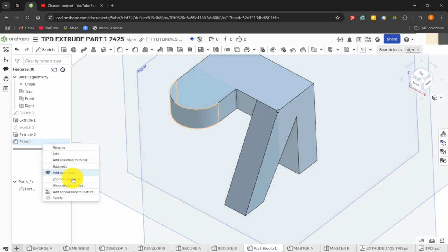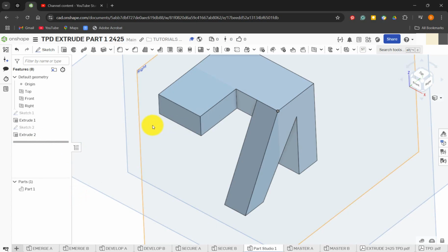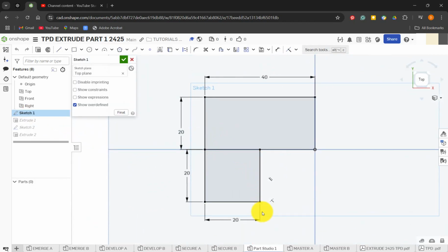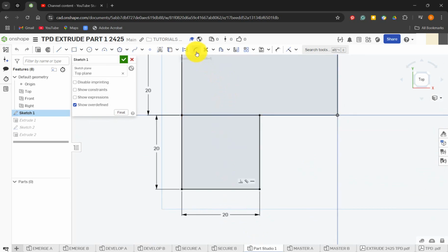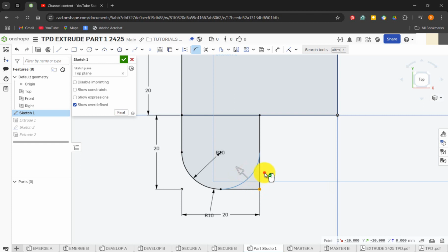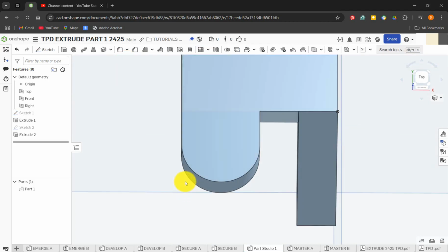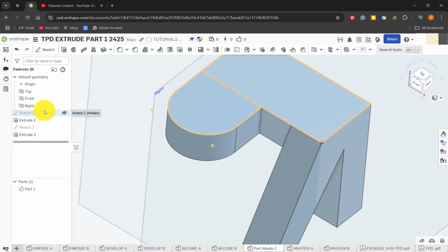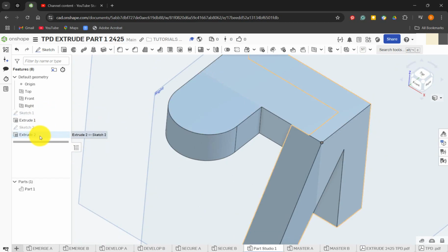If you don't want to do that, there is a different way, so let's delete that. So we could go into our original sketch, go edit, okay, but sometimes this can cause a few problems, we'll see. So if we go sketch fillet, click on that point, confirm that, type in the size, and again choose this one, click okay, and confirm the size, update that, let's have a look. Yeah, it's done the same thing as well. But then that feature's hidden in there. Okay, it doesn't really matter, but I just tend to use the fillets on there. I just find it a bit quicker.